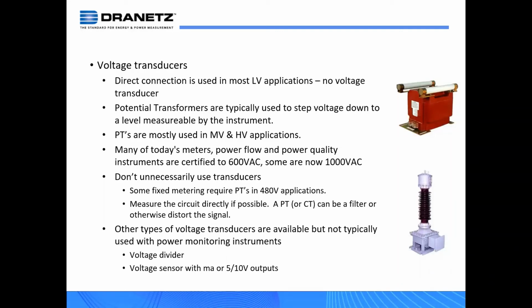As far as RMS events, they're usually not frequency sensitive. But when you get into what we call transient events, which are variations in voltage or current whose duration is less than one AC cycle, now there's a frequency component there. If you want to record those with any power monitor, you want to make sure that the in-between device is not attenuating them. So that's very important when you're deploying these devices.